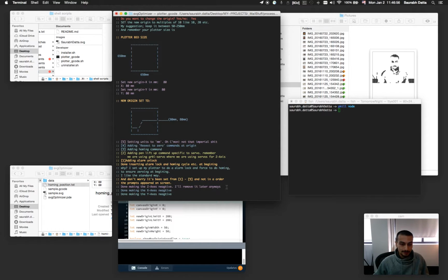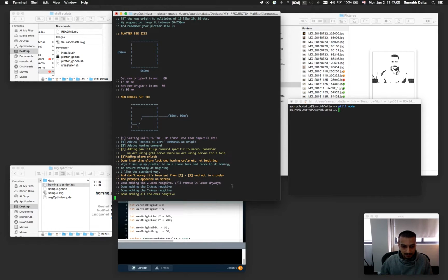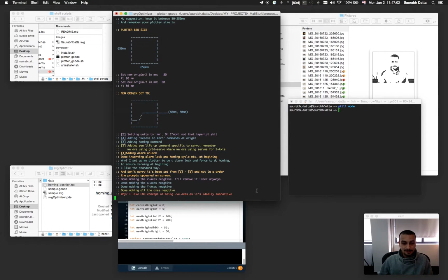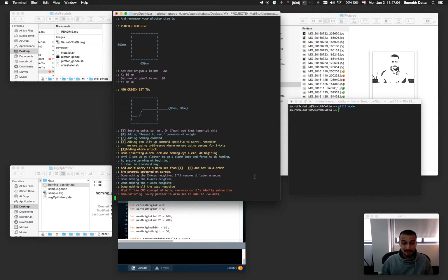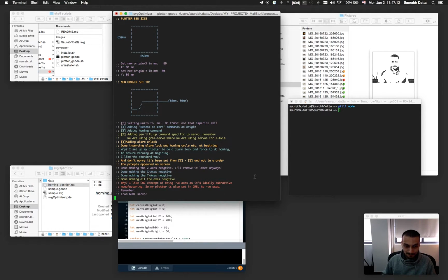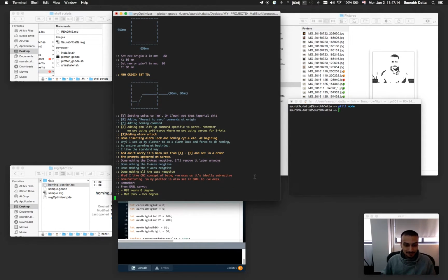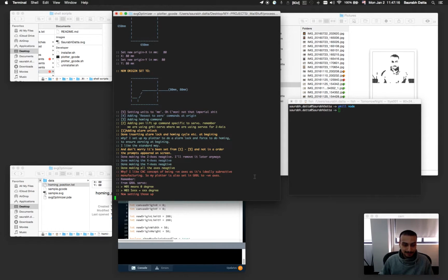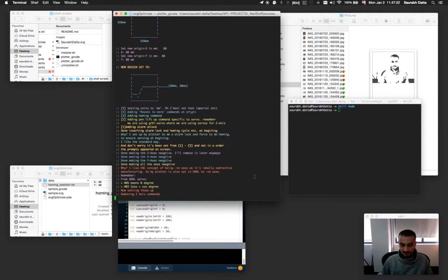So it's doing the z-axis negative, and it doesn't matter because I'm going to remove the z-axis. Then making all axes negative, because I'm explaining again, like here. Why? Because it's the ideal way of working with CNC type machines. And as I said, from GRBL servo, it's replacing every z-axis up and down with M05 and M03 commands.